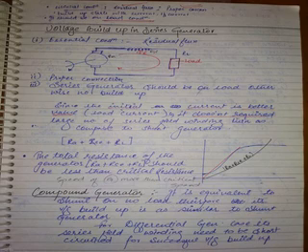The initial current flowing is a very small value. So to get a good amount of initial MMF, to access the residual flux and to develop the cumulative loop for successful build-up, you are intentionally making a large number of turns. That's the concept. Here, the initial current is due to load. Yes or no?